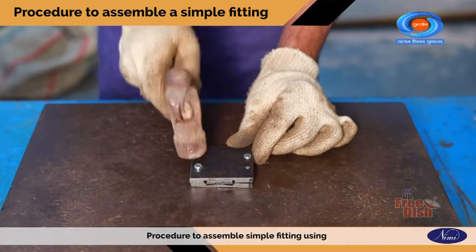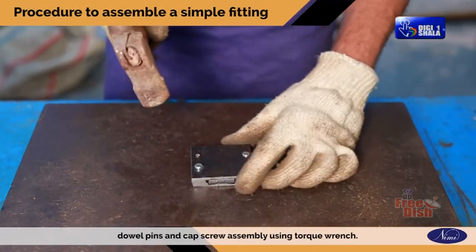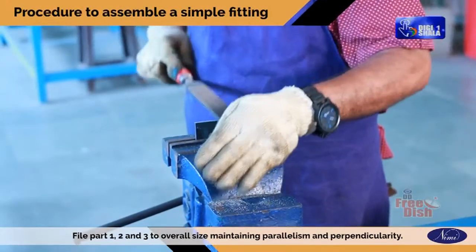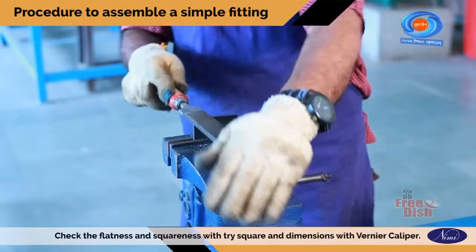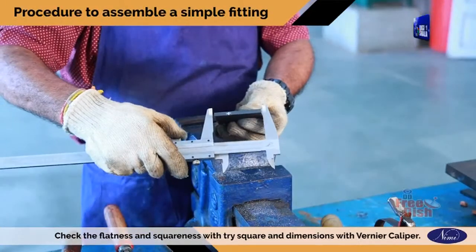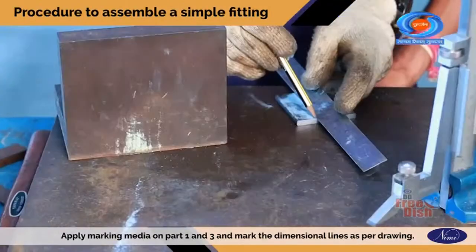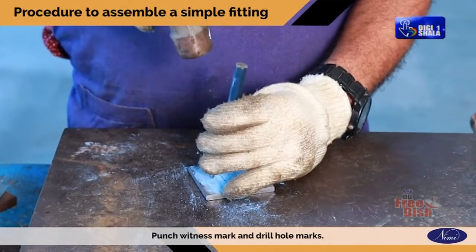Procedure to assemble fitting using dowel pins and cap screw assembly using torque wrench. Check the raw material size. File parts 1, 2 and 3 to overall size maintaining parallelism and perpendicularity. Check the flatness and squareness with a tri-square and dimensions with a vernier caliper. Apply marking media on parts 1 and 3 and mark the dimensional lines as per drawing. Punch witness marks and drill hole marks.